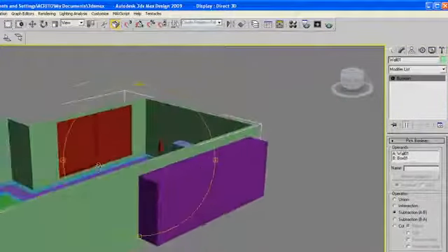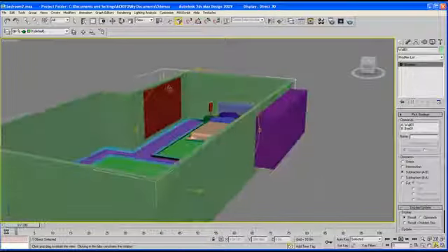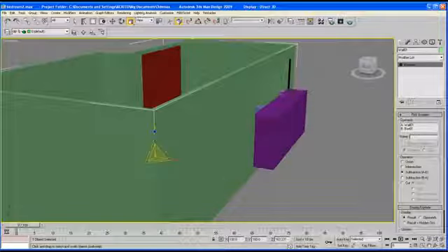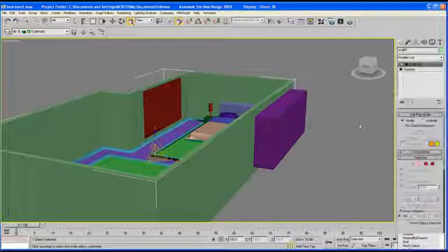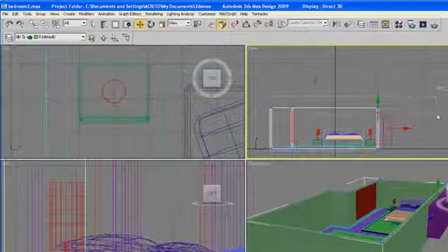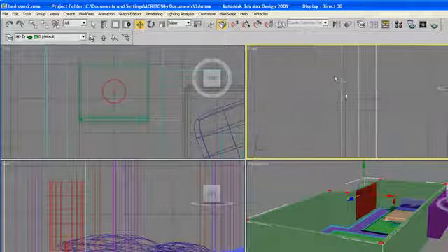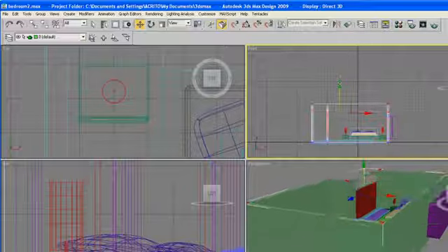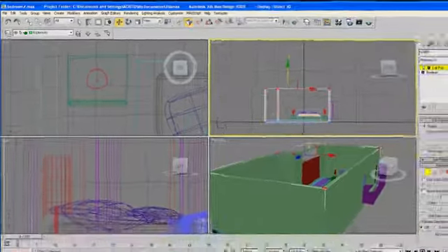We're going to have to increase the height of these walls. Because we turned this into a boolean last time, that's going to be quite difficult, because if we simply increase the size that way, we're going to have a massive gap here. What we want to do is apply the edit poly modifier. As soon as we do that, go over to the front viewport and select all the vertices up here, but make sure you don't select any of these. And now we can click and drag them up. So don't worry about that, we'll be sorting that out later.